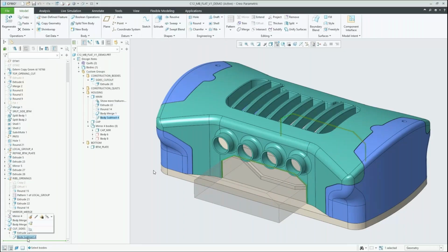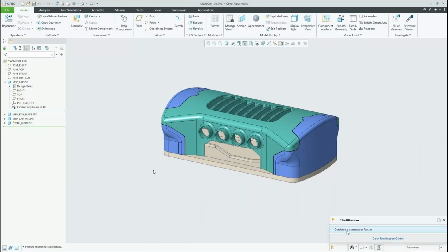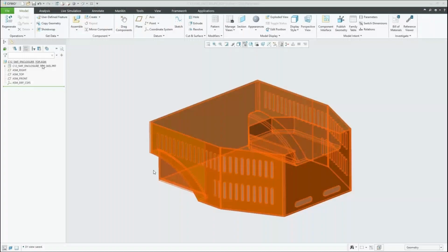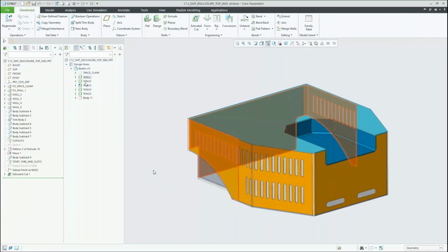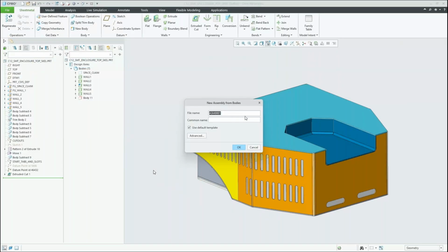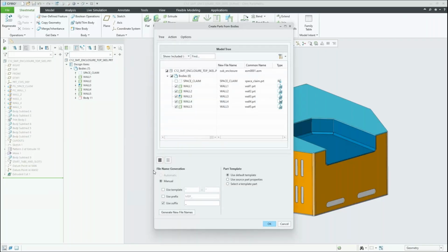This means also if I'm changing my part, now with notification, if I'm changing my default part, my skeleton kind of, you'll see that it will calculate here as well. So it's linked to each other. The same as with a sheet metal part. The function that we showed here is in a skeleton part itself. It is not necessary. It can be done in a general part as well that you use or give the name skeleton. It is the same way that we've done here.